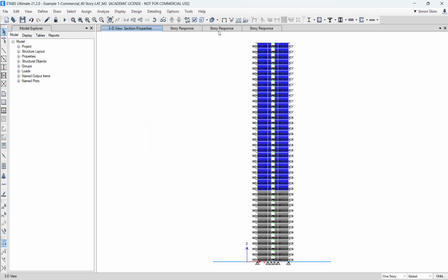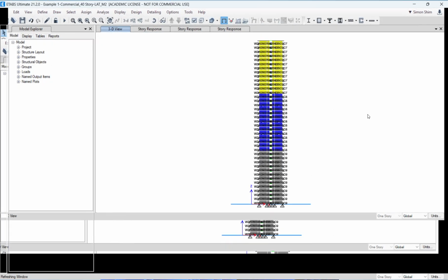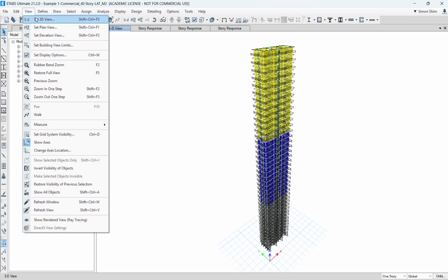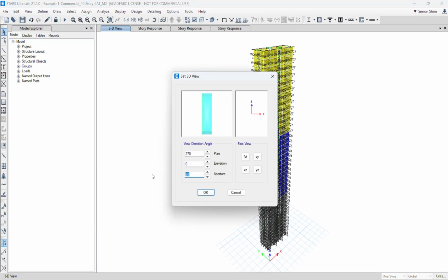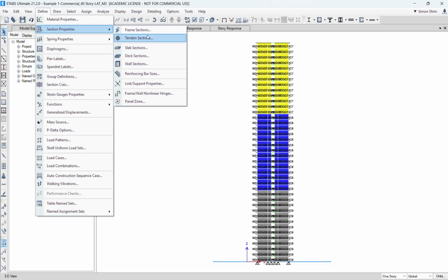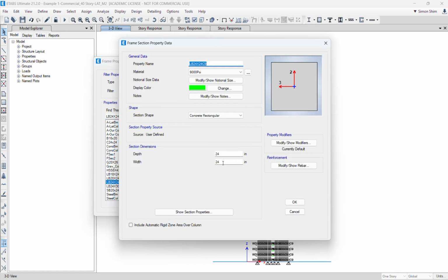Let's refresh. Okay, so you see that? 28 inches, 24 and 20 inches. We only changed the wall. Now, basically, you need to change the link beam thickness and width as well, together. So go to the frame: the link beam before was 24 inches by 24. You need to change the width to 28 to match the wall thickness.